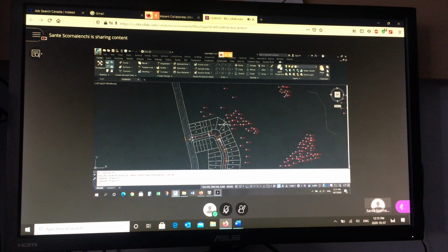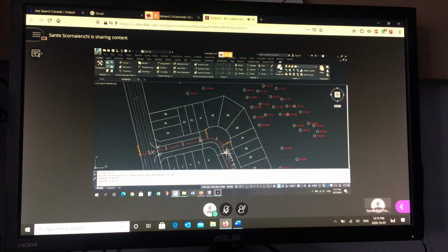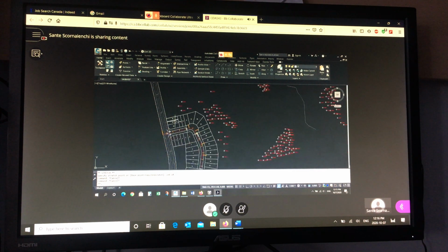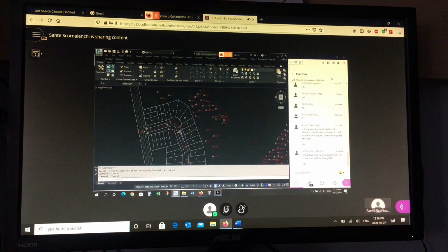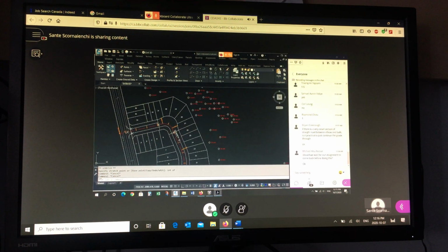So if you do make a mistake on your gutter line, you can just project the point to the new position and then adjust your profile. I'll show you how to do that. Does everybody understand this technique of projection? It's a really simple tool, and you don't have to remember the number of the station or the elevation of the surface. You draw stuff, you're using geometry, and you're leveraging the function to take a point in plan and show you where it is in the profile. Very simple tool. Okay? And we're going to use that tool many, many times, but this is one of them.